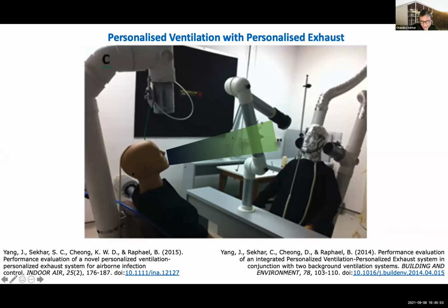So this mannequin is the patient coughing out, or not exactly coughing, but spitting out infectious aerosol. We use a tracer gas, like say CO2 in this case, to mark that, and then see how much of that is being inhaled by this mannequin. And we have all this, shoulder, we call this the shoulder exhaust, and then we call this the head exhaust, top exhaust. And we found when we have this exhaust operational for the patient, if this is a doctor, let's say, the exposure of this infectious aerosol is considerably reduced for the doctor.